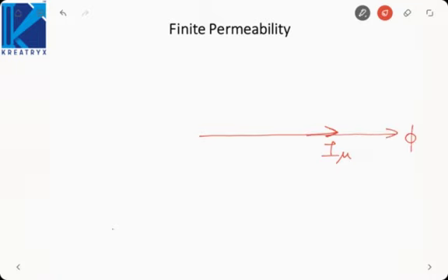Now we saw that the induced EMF in primary and secondary winding was lagging the flux by 90 degrees. So here I am representing E1 and let us represent E2. Here I have shown E2 is greater than E1. That is just an assumption, because I am considering a step up transformer. That is why the length of E2 is greater than the length of E1.